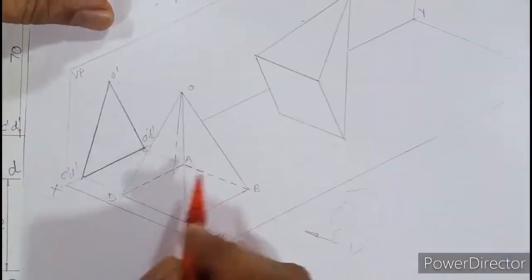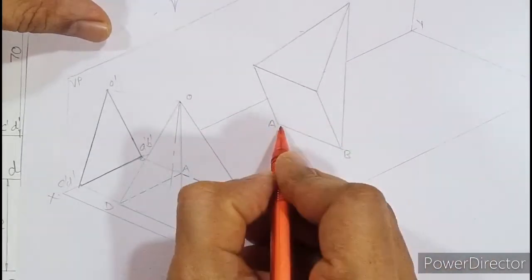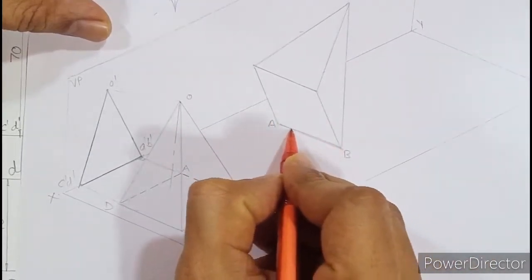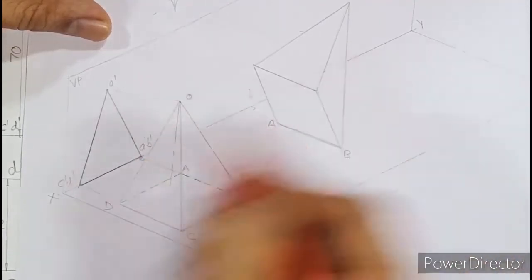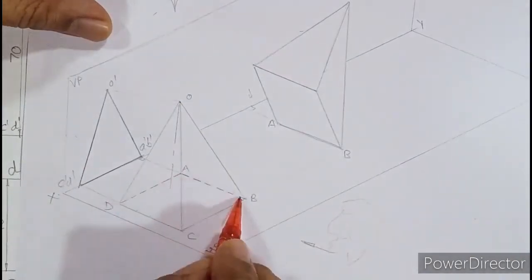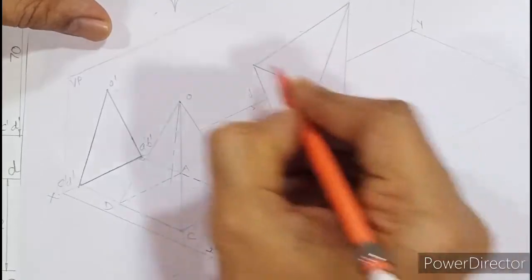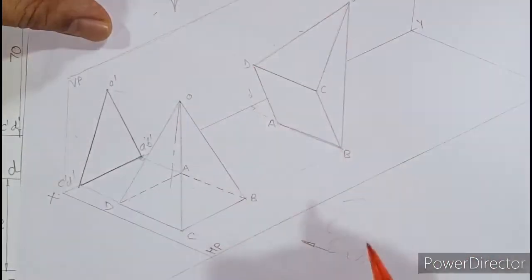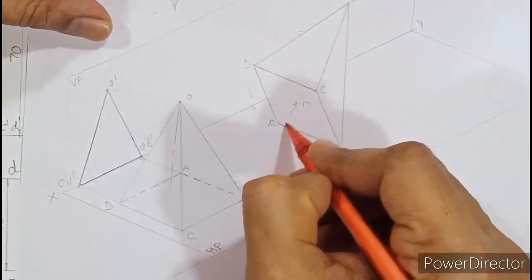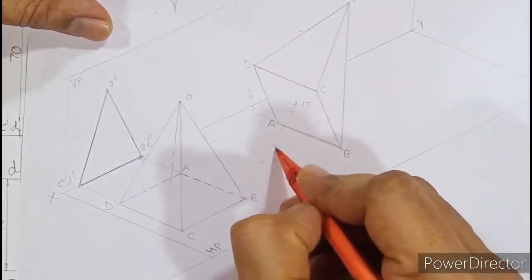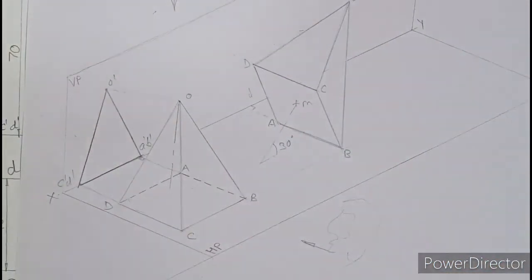So look at this. When you tilt the pyramid, this AB is the base edge which is on HP. Can you make out? And if I extend this AB and look from the top, that is perpendicular with XY or VP. So AB was here. After shifting, AB will still remain in contact with HP. CD will be in air and O will be here. And also if you try to draw the axis, suppose this point is M, and if I extend this, the axis will make 30 degree with HP.